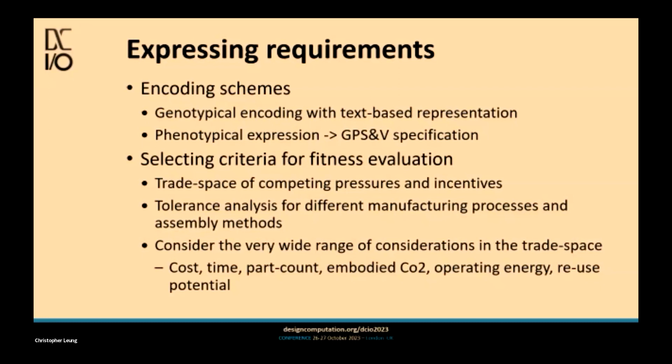And this is where I think there's the key opportunity of trying to couple the manufacturing requirements through the whole of the process, and linking them to the trade space that, as a design for manufacture practitioner, you'd be thinking about: the competing pressures for time and cost and equipment availability and skill level. And this provides a framework, I think, for doing that, for trying to couple the actual description of the functionally critical parts and just putting precision where it's needed and not everywhere. Sort of stop treating CAD models as only nominal, and doing so at an appropriate scale.